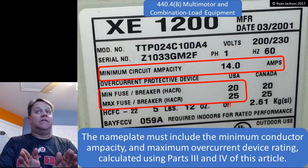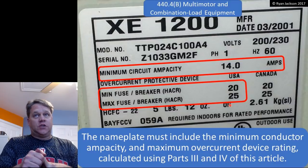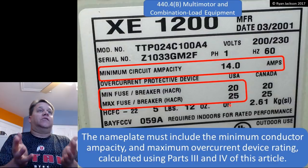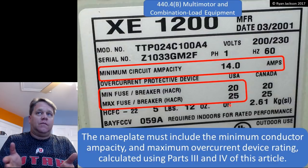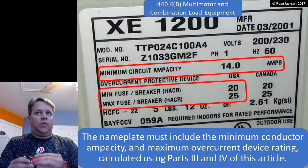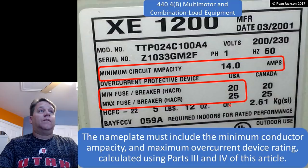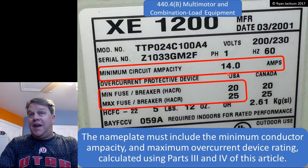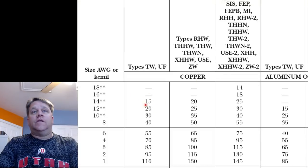So we have ground fault and short circuit protection. We have to agree on that, right? We know it has ground fault and short circuit protection. But that's not all when it comes to overcurrent protection. We have to have overload protection as well. If I put 14 gauge wire, which is good for what? 15 amps.